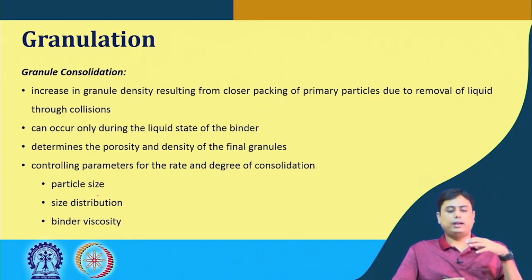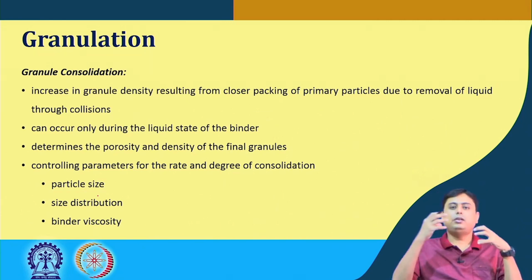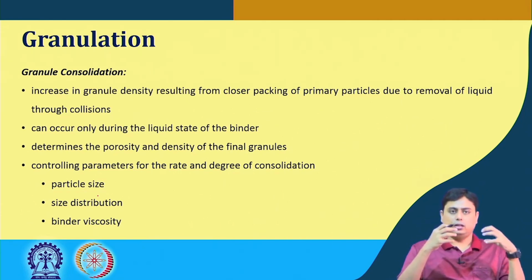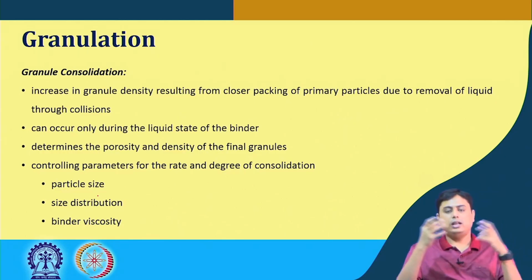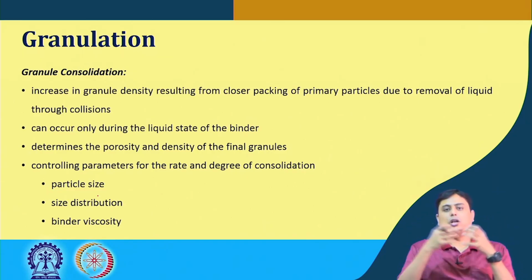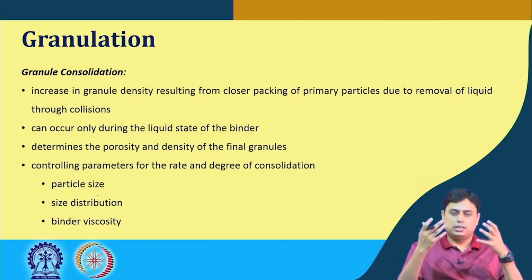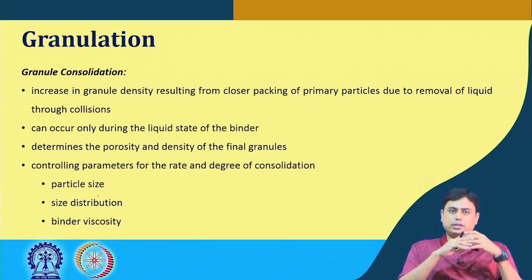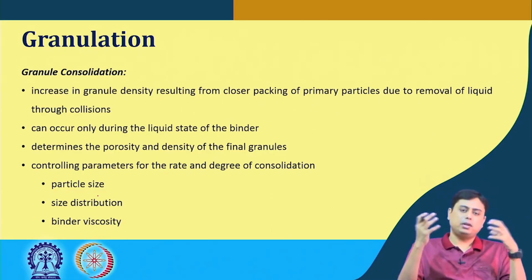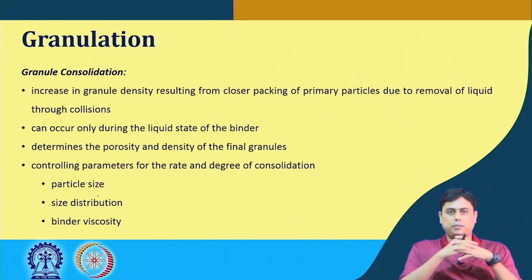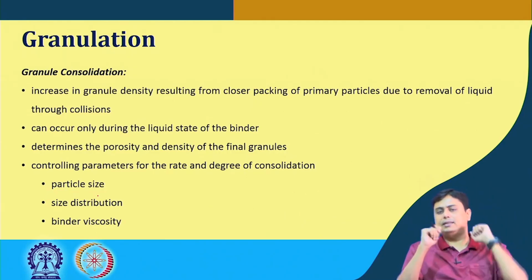Now, if we look at the granule consolidation, these granules that have been created by this wetting, this increase in the granule density resulting from the closer packing of primary particles due to removal of liquid through collisions is what is called granule consolidation, and this can occur only during the stage when the binder is still in the liquid state, because that liquid can escape and it can be compacted or consolidated. This consolidation step basically determines the porosity and density of the final granule.